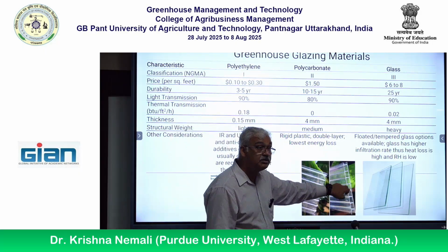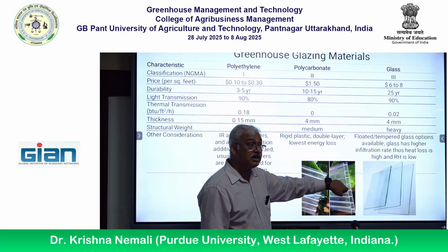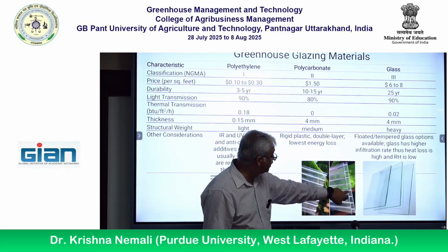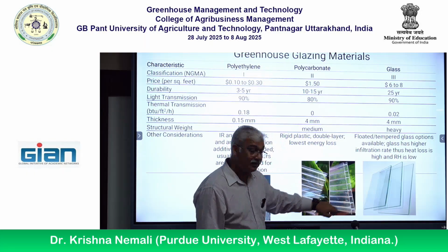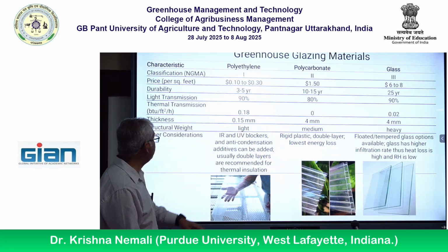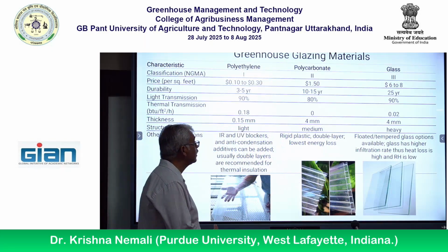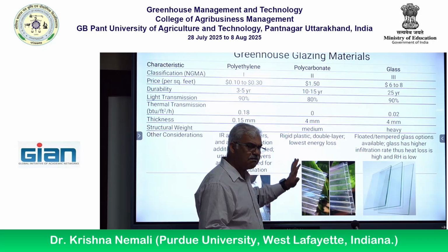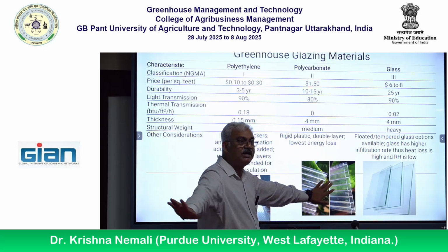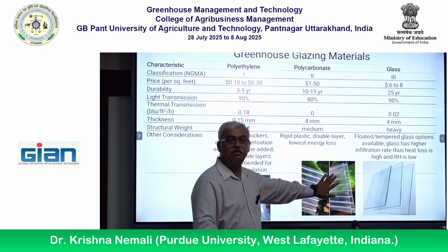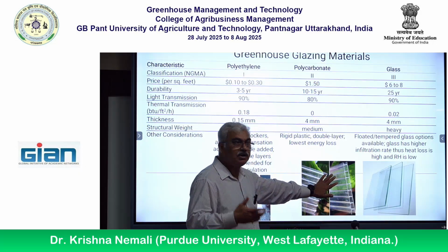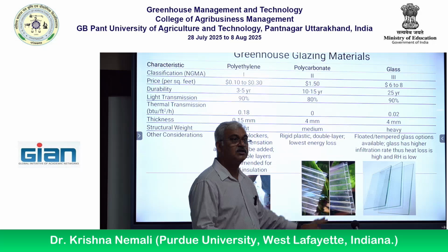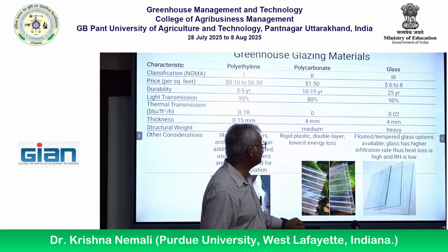Okay. Here is an example of double polycarbonate. You see there are 2 layers, and in between there is air. So the material comes built in like that. You see that there's a gap right there? That's air. Okay. But we recommend it for thermal insulation. If you are concerned about heating losses, the best is polycarbonate, because it's not going to let any heat out. But it's probably not popular here because you're not really concerned about heating losses. What you're concerned about is cooling issues, right? So that's what it is.